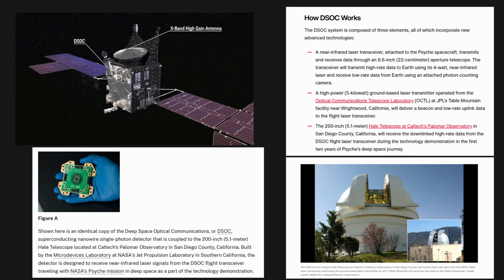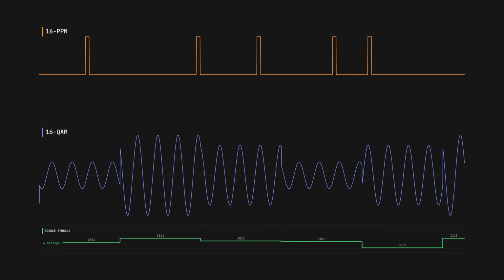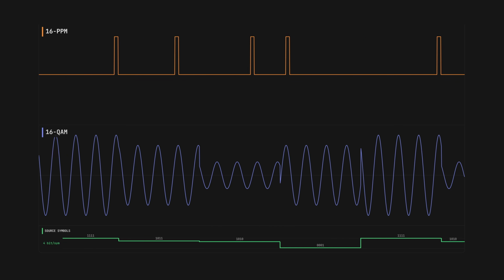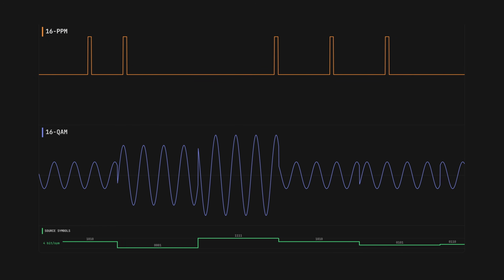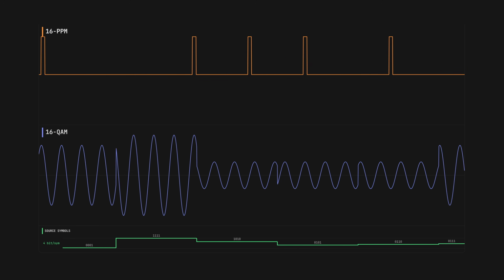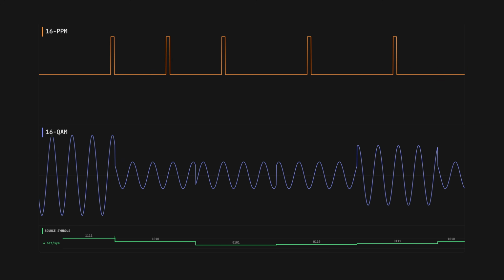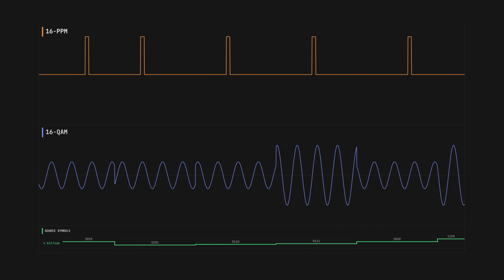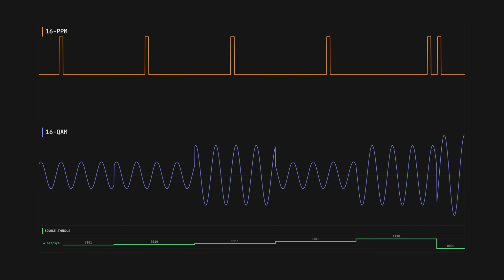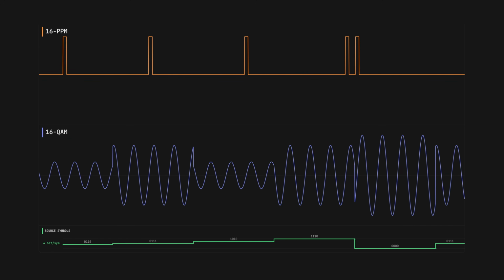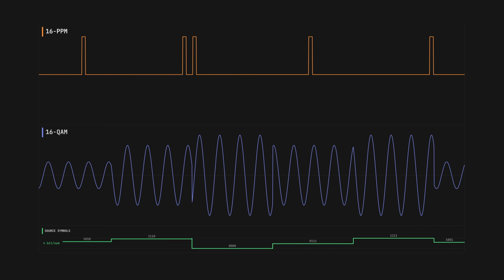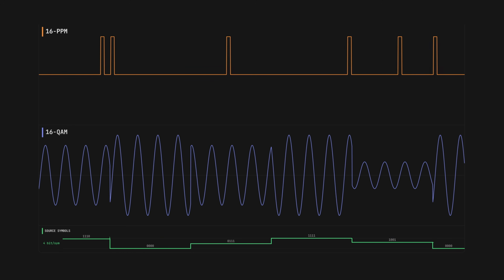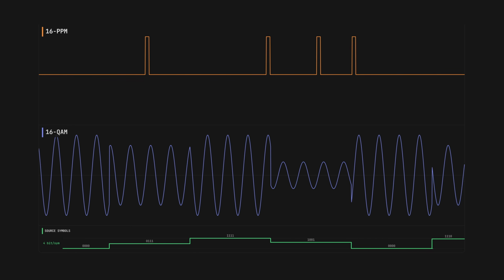centimeter satellite telescope. Using pulse position modulation generally results in better photon efficiency because a single photon can carry multiple bits of information based on when it arrives, a theoretical maximum of 4 in this 16 PPM example. In higher order PAM or QAM, multiple photons are needed to determine accurate average intensity, and even PAM2 at its theoretical maximum can only achieve 2 bits per recorded photon. The downside is that PPM has lower spectral efficiency.